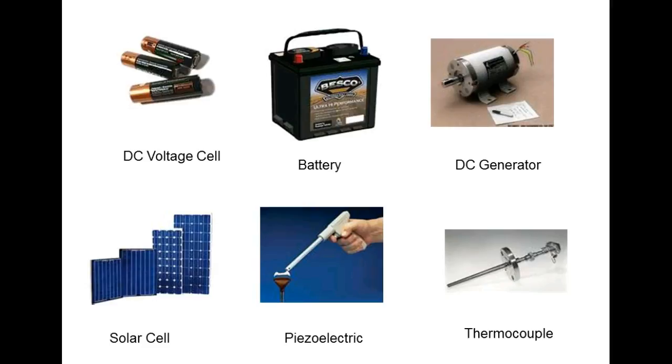So why did we start calling these things batteries? But they're not really batteries. Now, a 9-volt is a battery. If you take a little 9-volt and strip it apart, you'll see 6 little cells in there. So a 9-volt battery is a battery. These guys here have 6 cells built in. That's why you have 6 caps on top when you put water into each cell, right? Each of them makes 2 volts per cell, so that gives us 12 volts, right?